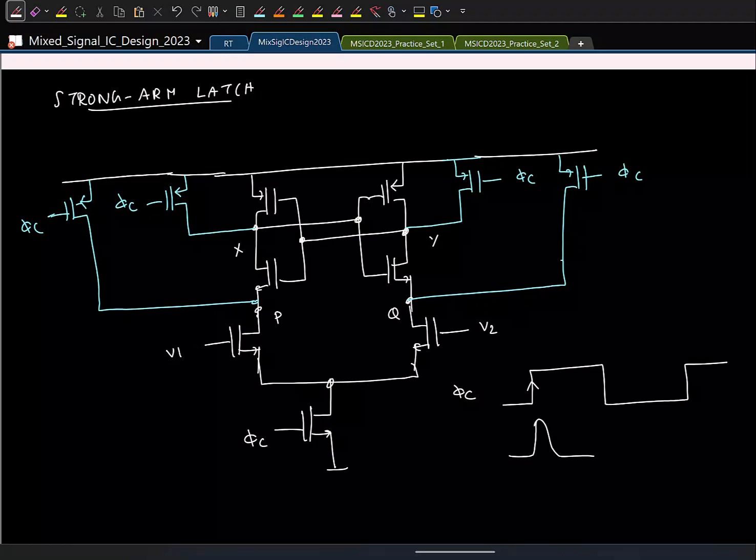This is the rising edge, and let's say once phi c falls to 0, what happens? At this point, we are basically trying to pre-charge all these capacitors to VDD. So if you take any node X, we'll have a capacitor, and we are connecting it to VDD through a small on resistance. So what is the current drawn?